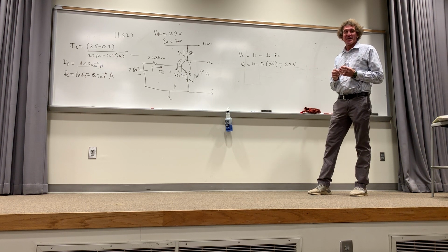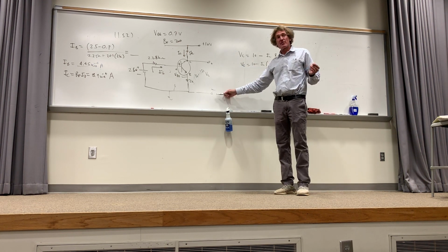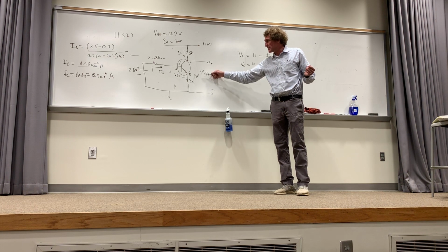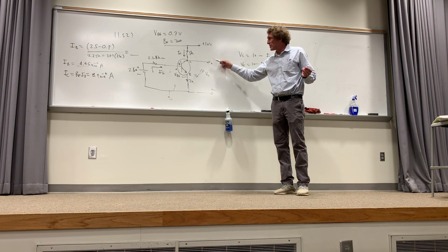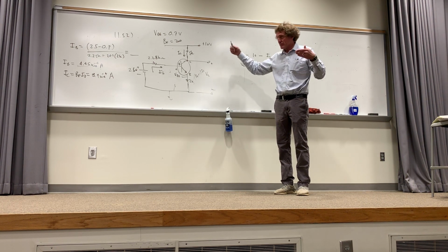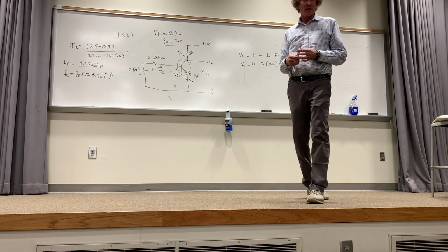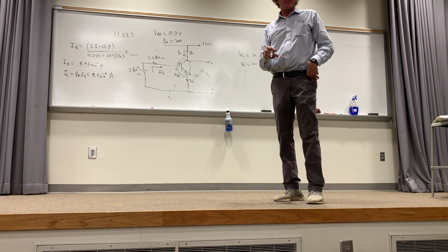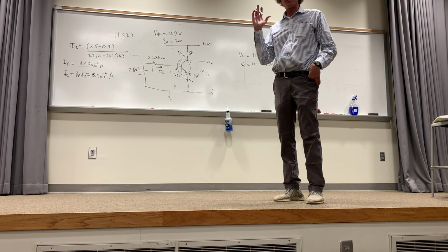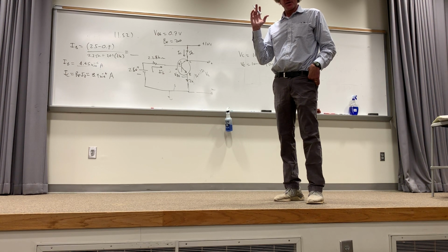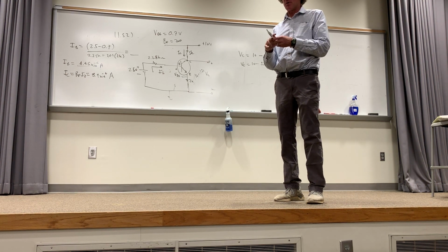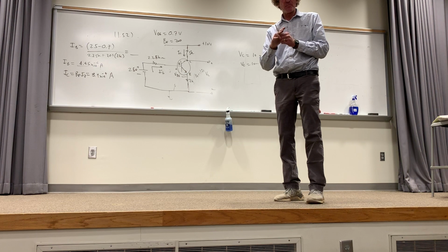Why is the emitter resistance not factored into the VC? They only want the voltage from here to ground, right? Right. They don't want it from collector to emitter. So the only voltage that you have to worry about taking off, you might say, is that. Okay, I see it. All right, you all see what I've done there, right? It's not hard if you stay tuned, and I'll give you problems, but I want to make sure everybody's clear on that. You got me?